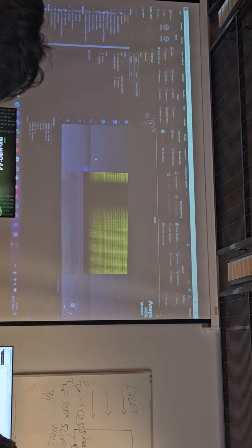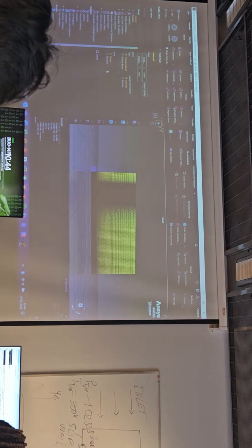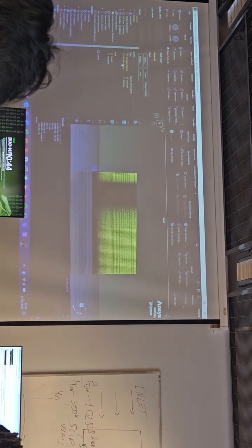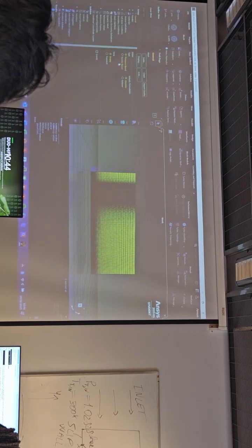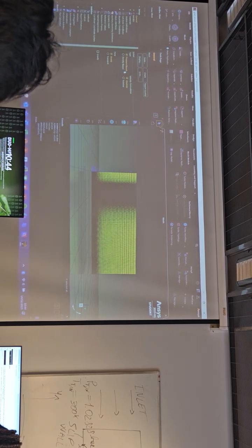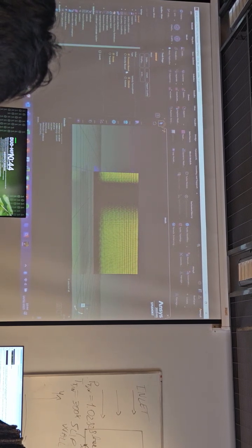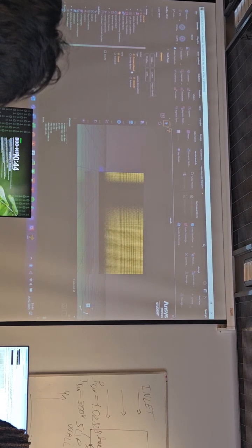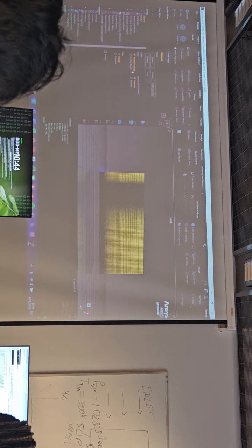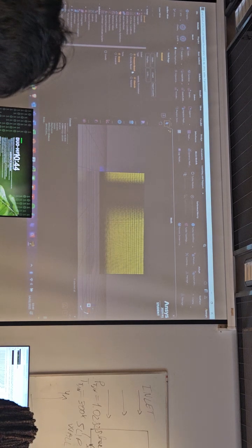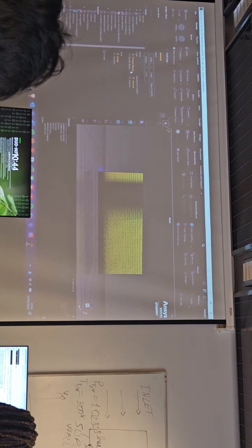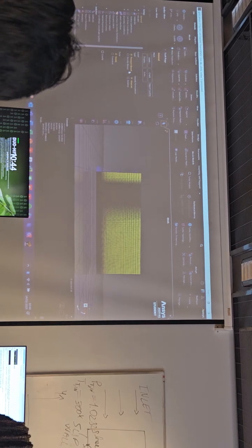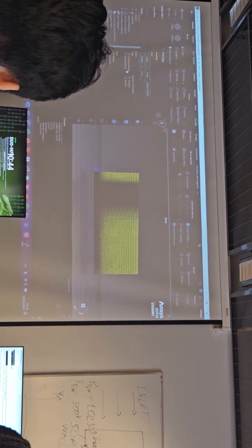So in general, we can set some solver options, pressure-based or density-based. Typically, pressure-based is for incompressible flows, density-based is for compressible flows, but it's not always the case, I would say, it depends on the case. By the way, in this course we'll always use the pressure-based solver.